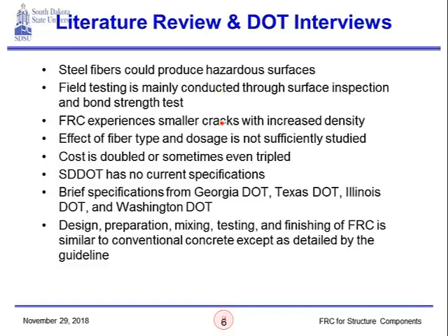FRC experiences smaller cracks, as I said, with increased density. So we have more cracks with FRC, but they are smaller in size, which basically serves our purpose of making sure we increase the durability of concrete. Effect of fiber type and dosage is not sufficiently studied. We rarely found any studies where they actually look at the effect of different fiber types and different fiber dosages on certain properties of the FRC, which is something that we are focusing on in our experimental procedures that we followed for this research.